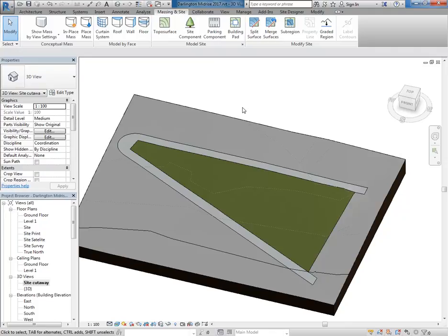Okay, so we'll start doing a site analysis drawing in class, but what I see a lot of people doing is try to do it all in Revit and do all this shading and everything, and so you end up with so many topo surfaces it's not funny, and then you never need them again later on when you're doing the more complicated things. That setup isn't going to work anyway. So I'll show you some other ways of doing it instead of just using subregions for everything, but yeah, get a few in for the main things like the roads especially would be good.